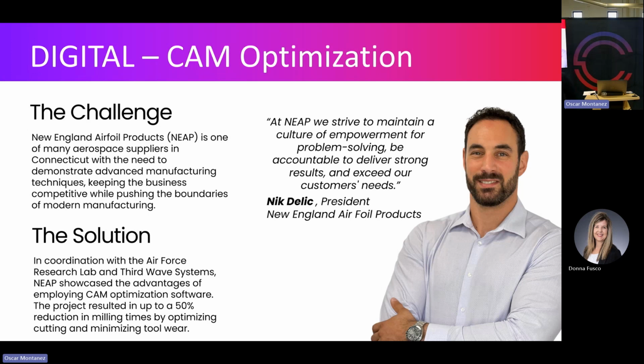Yeah, absolutely. So I skipped over a whole other subject, and we're actually going to have a future event on automated inspection. But model-based definition, particularly the QIF file, the Quality Information Framework, is quite a mature file format. It holds your CAD geometry as well as your PMI and metadata. So it can actually hold CMM points. It can hold inspection data. If you're actually inspecting the parts, you can encode that back in the QIF. So it's a mature file type.